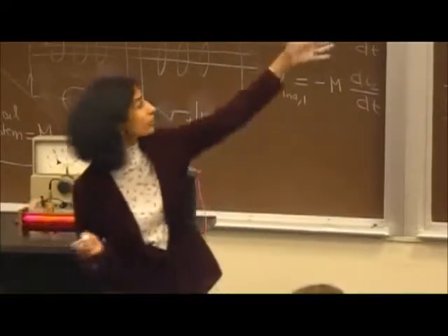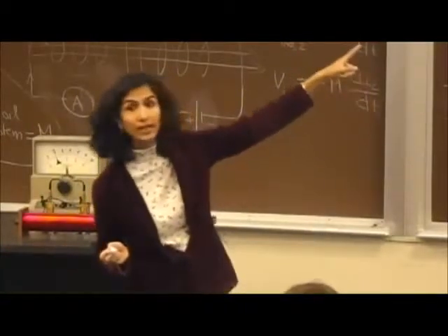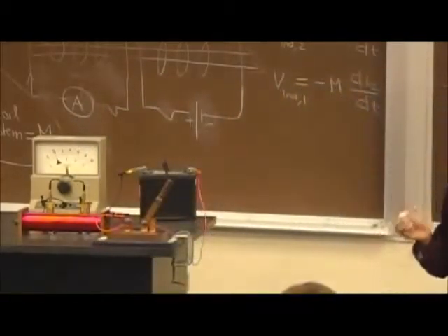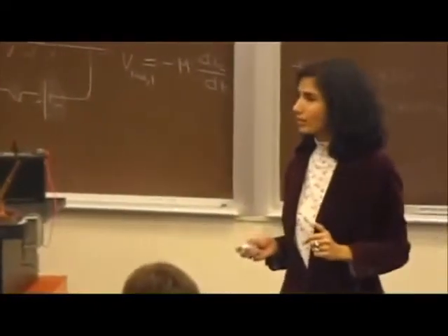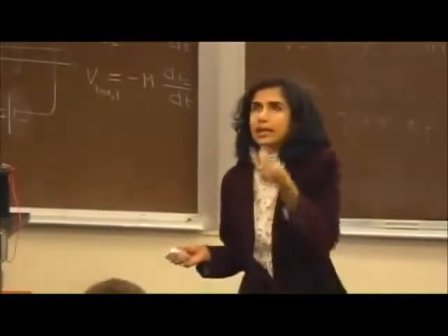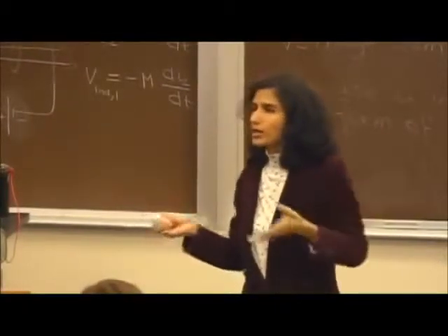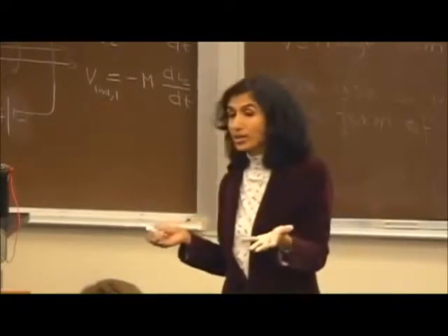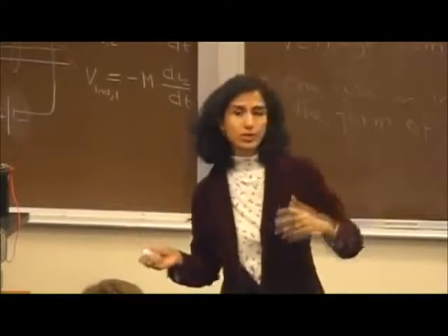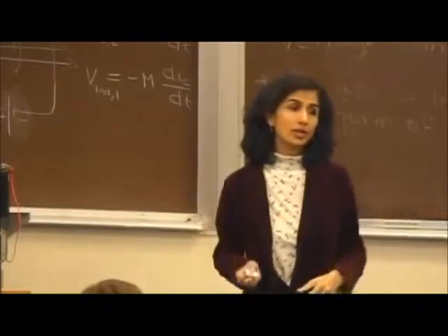If you send it at high voltage, first case is better. That was high voltage, V1 was greater than V2, right? Higher voltage and lower current is better because in this case you are losing less in the form of heat in the wires. Is everybody understanding that? Of course, there are limitations. You cannot make the current extremely low in these wires and the voltage extremely high. So of course there are some technical limitations, but does everybody appreciate you should try to make it as low of a current as possible within your constraints in order to minimize the power losses.